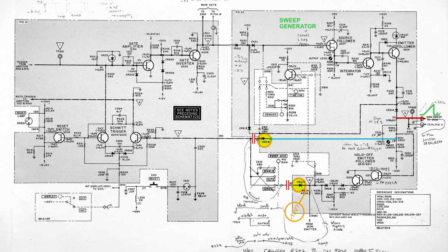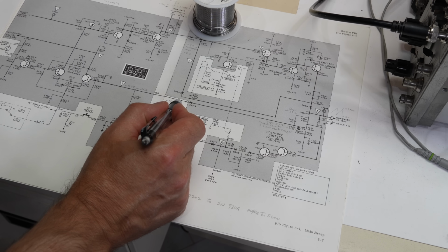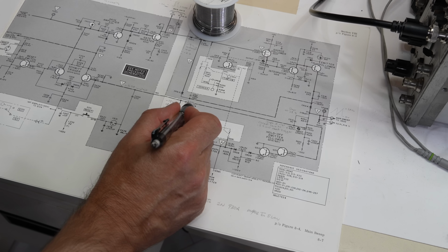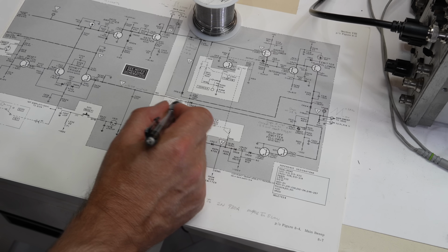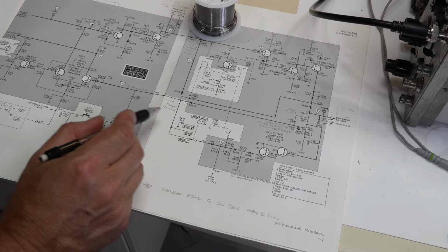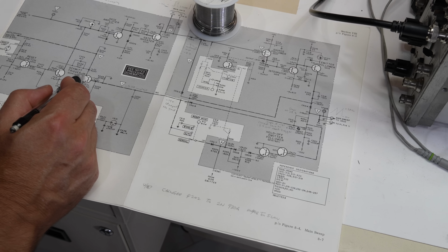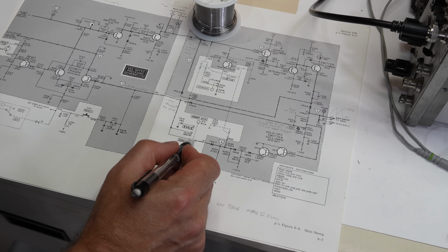I'll get one sweep. So something brings this side minus 13 volts. As soon as it reaches minus 13.6, this diode turns on, and then it gets pulled down by this and never raises, right? Either this side is pulling it down or that side is pulling it down. Let's make sure the hold-off emitter follower is not causing it.